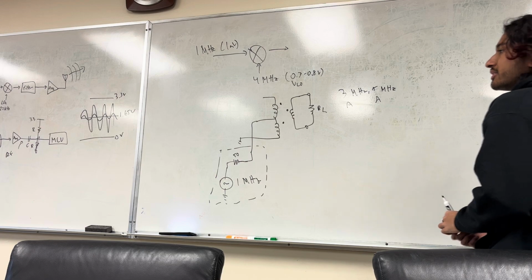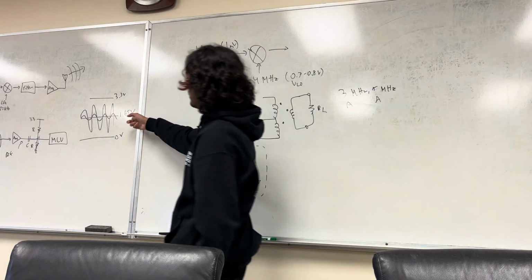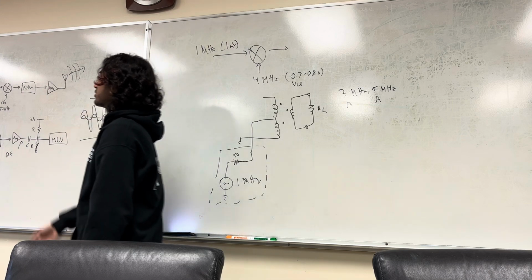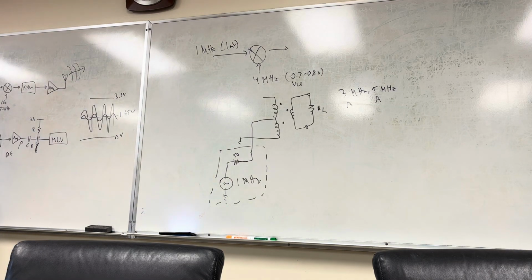Another nuanced thing is just like how on the receiver, we need a certain amount of dynamic range that we would like to maintain. Over here in the transmitter, we can have a DC bias, 1.65 volts, right? We can have a certain amplitude signal, but we're not going to send a really small amplitude signal out from our transmitter, from our MCU here. That'd be a waste, right? Why send out a small signal and then have to amplify it more over there? We can make it larger here, so that our front end has to do less work to transmit it.